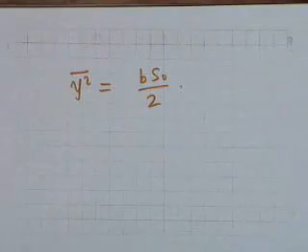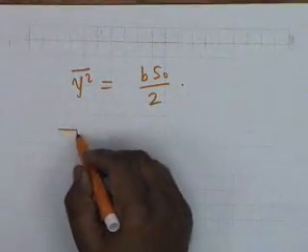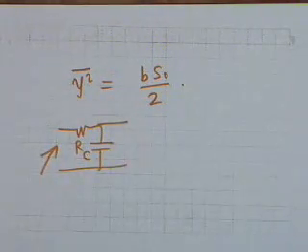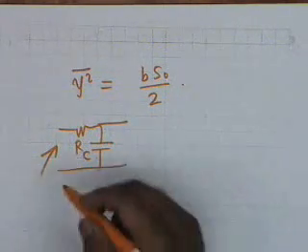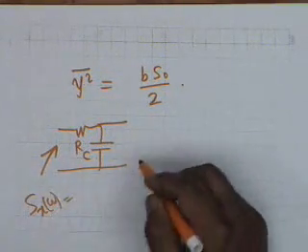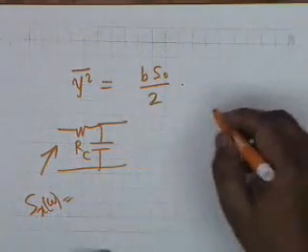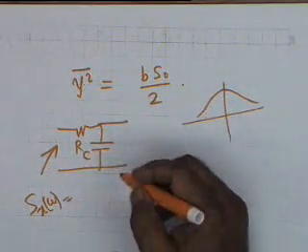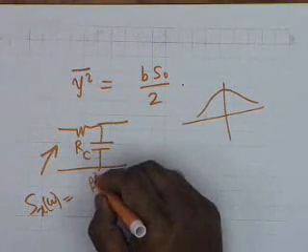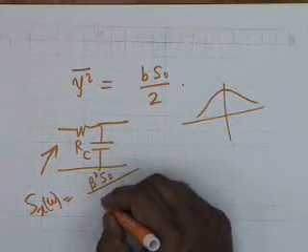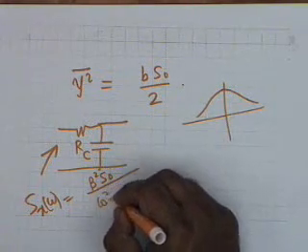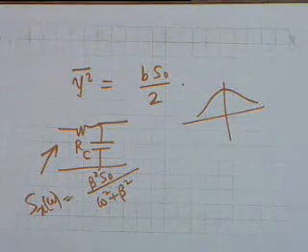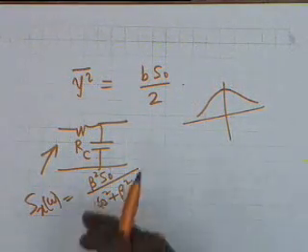All right. We take a next example, the same RC network, but the input process is not white, it is colored noise. You recall that a low pass kind of noise would have a spectral density like this. We took an expression earlier, which is beta squared S naught divided by omega squared plus beta squared. What is the autocorrelation function of this? What is the inverse transform of this?